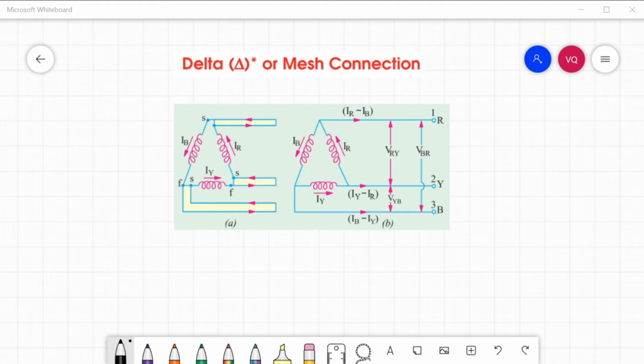It might look as if this short of interconnection results in short-circuiting the three windings. However, if the system is balanced, then the sum of the three voltages around the closed mesh is 0. Hence, no current of fundamental frequency can flow around the mesh when the terminals are open. It should be clearly understood that at any instant, the EMF in one phase is equal and opposite to the resultant of those in the other two phases.